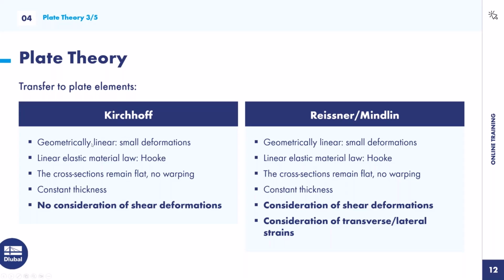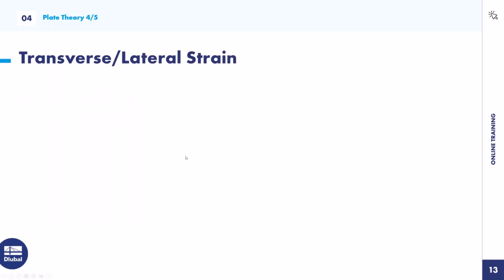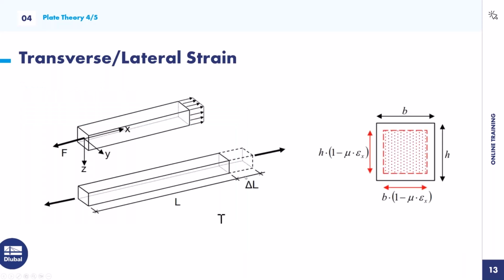We could have also taken just the Kirchhoff theory. Now, what the Poisson's ratio means: it defines the ratio in this equation. If you pull a beam and it gets longer, the new volume right here must come from somewhere, right? And it comes from this place here.